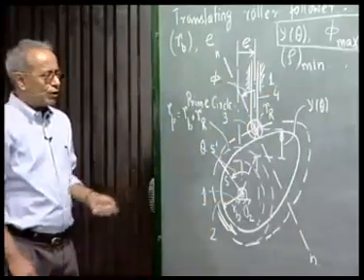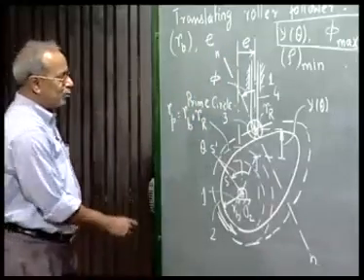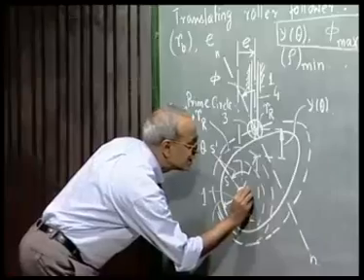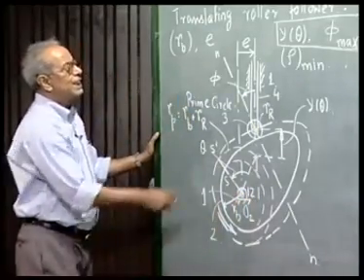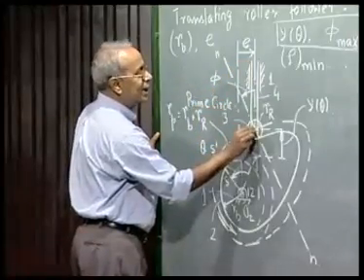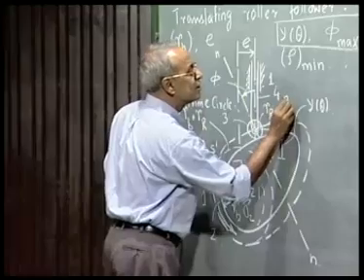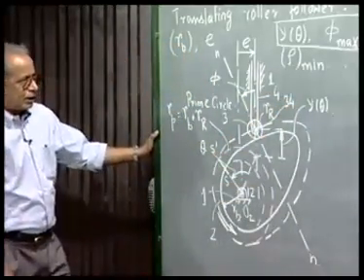So it is a 4-link mechanism. Between 1 and 2 there is a revolute pair at O2, so this is the relative instantaneous center 1,2. 3 and 4 are connected by a revolute pair here at the roller center, so this is the relative instantaneous center 3,4.